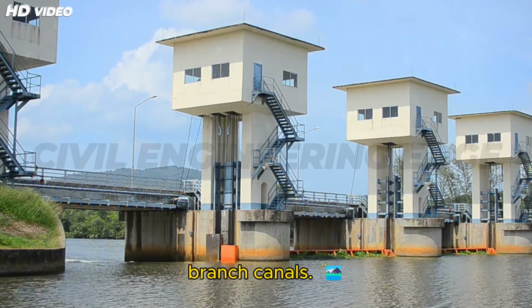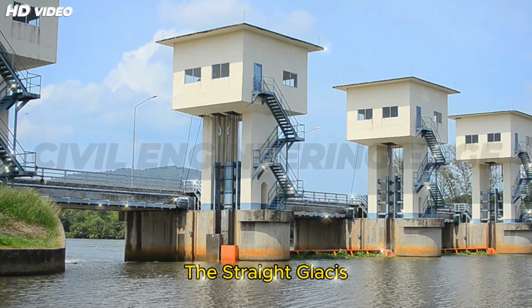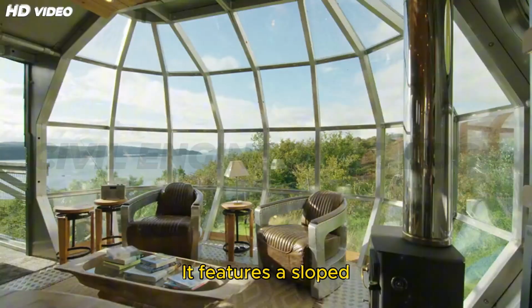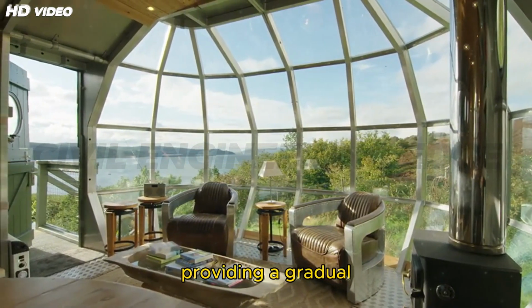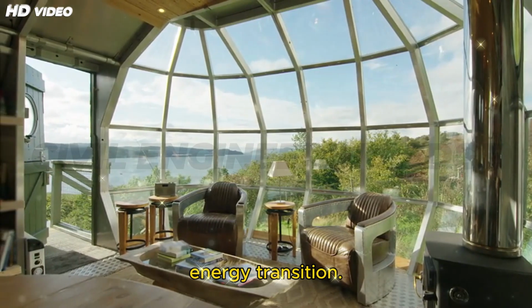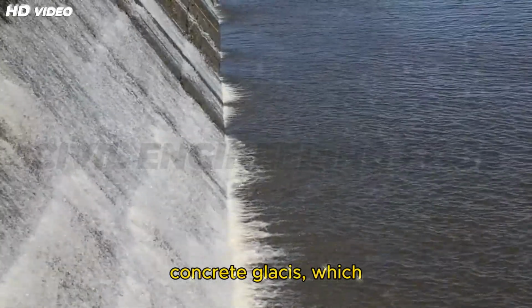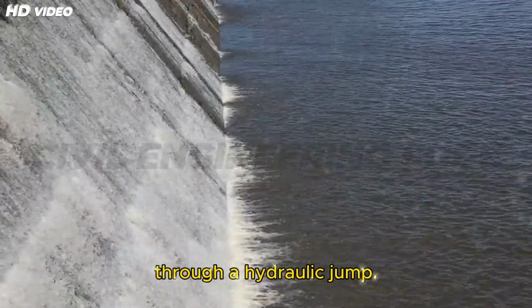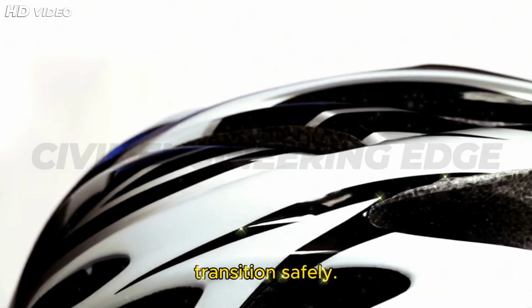Segment 8. Design of a straight glacis fall. The straight glacis fall is a modern structure designed for medium to high discharge canals. It features a sloped floor glacis instead of a vertical drop, providing a gradual energy transition. Structure: the upstream crest leads to a straight inclined concrete glacis, which drops the water to a stilling basin where energy is dissipated through a hydraulic jump. This design allows high-velocity flow to transition safely.